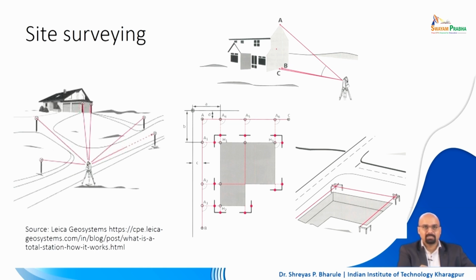For example, there is an existing structure right there on the site. So, you will put down your total station and measure the apex of it, so as to understand whether the angle of the total station is identifying it correctly, and then you will get additional reference points on the site, like here it is mentioned B and C, right.